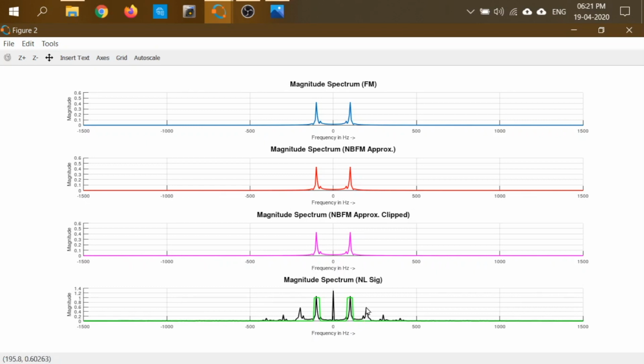If you want to have it at 2 omega c, you can put the same filter at 2 omega c, but you have to make the width of this filter larger, because there the frequency deviation will also be made twice. This is what we have studied in frequency multipliers, right? Not in the case of frequency mixers. Frequency mixers will just shift the frequency. They will not make delta f twice, thrice, etc. So that's what we are going to do. So this is the thing.